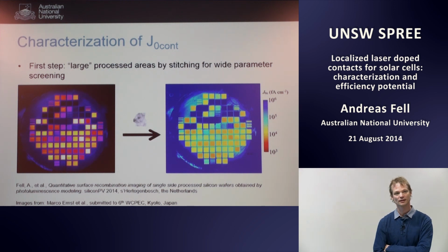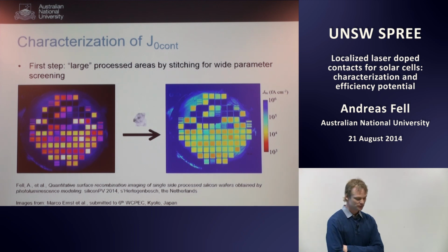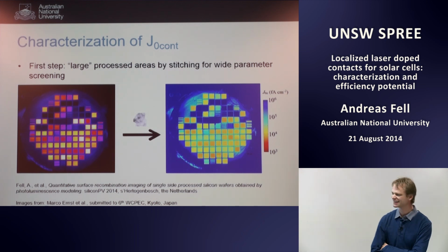Did you try Suns-VOC measurement on your cell? On that 90% efficient cell, you said that you think that it's most likely some resistance problem. So Suns-VOC would give you some good idea of what it could be with a better series resistance.